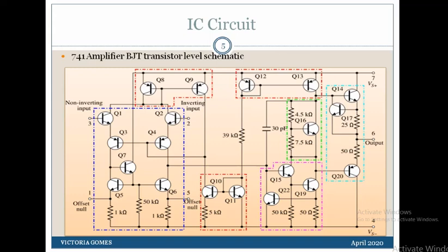The design of this circuit is extremely clever because it eliminates the need for an emitter bypass capacitor. For this and other reasons, the differential amplifier is used as the input stage of almost every IC op-amp. We'll see this when we discuss the different stages of an op-amp.